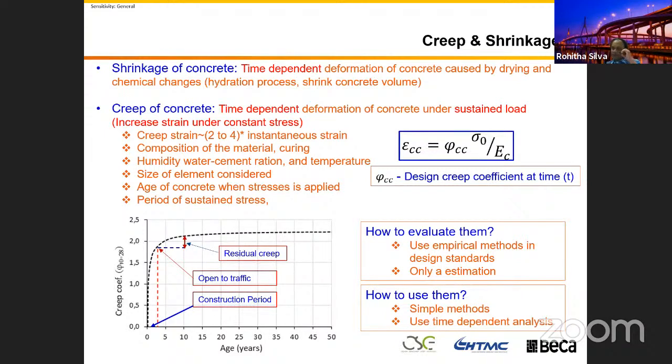If you don't cure properly, even we have experienced, because of the shrinkage you get cracks on your bridge deck. And because of creep and shrinkage, if not properly designed, I have seen prestressed concrete bridges, after you construct the bridge and leave it for some time, the bridge will hog. You can see the impact when you look at the barriers, they are shaped like they have a camber, free of charge camber in the barrier. If you do not properly detail them, they will crack.